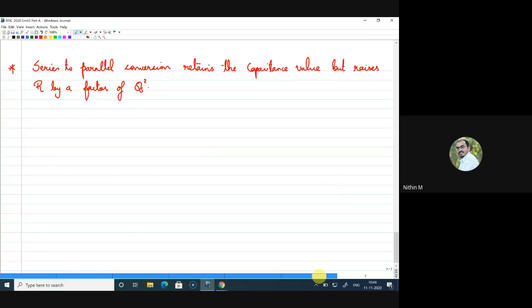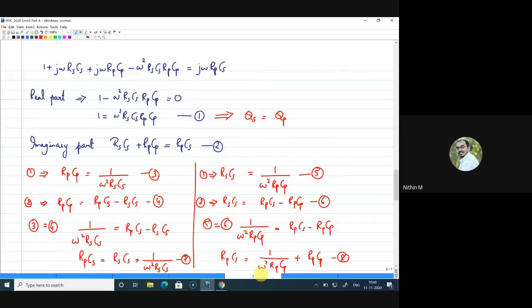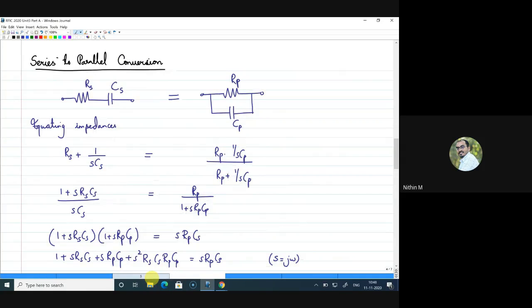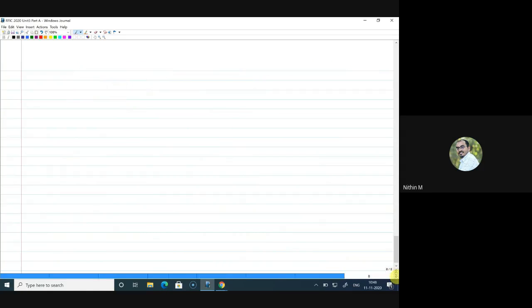Maybe this derivation will not give you much idea. Let us take one simple example and see how we can actually apply these techniques to convert resistance from lower to higher or from higher to lower. We'll start with a very simple technique, which I'll call a basic matching network.